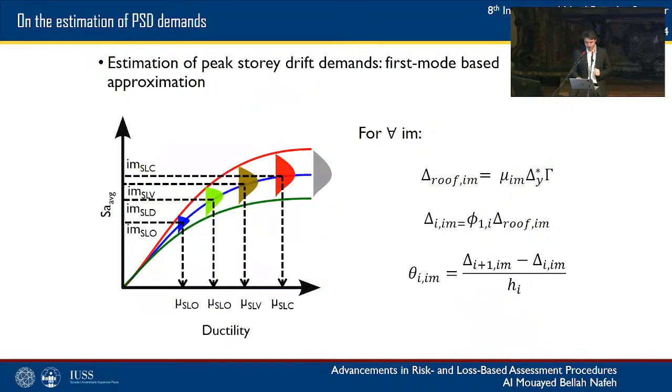Thank you very much for your question. So we've explained along the way what were the approximation methods that we used to derive those EDP quantities, meaning the peak story drift, peak floor acceleration, and residual peak story drifts. So we've decided to integrate based on the dynamic strength deformation relationships that we get from the tool, a series of approximations.